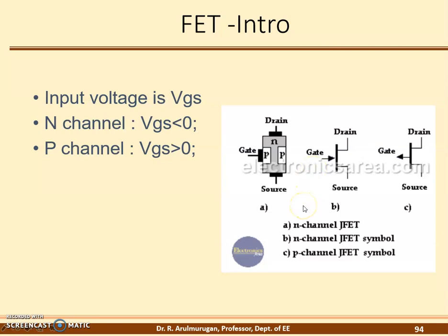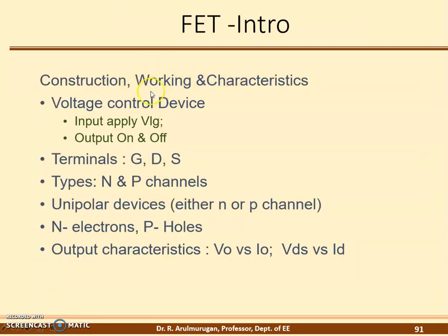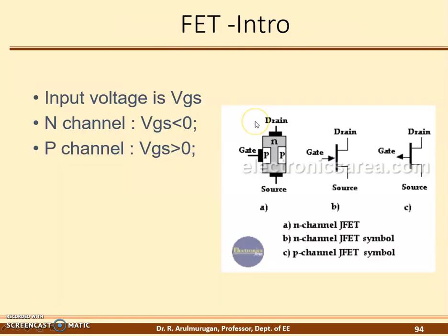So far I have explained about construction and the introduction, and I have touched on the characteristics. Further, we are going to see the working of the FET and its characteristics. Here, keep one more point in mind: whether you conduct a test for N channel or P channel. For the N channel, you apply an input voltage less than 0 voltage. For the P channel, just the opposite, you apply an input voltage greater than 0. This is one of the major important points.